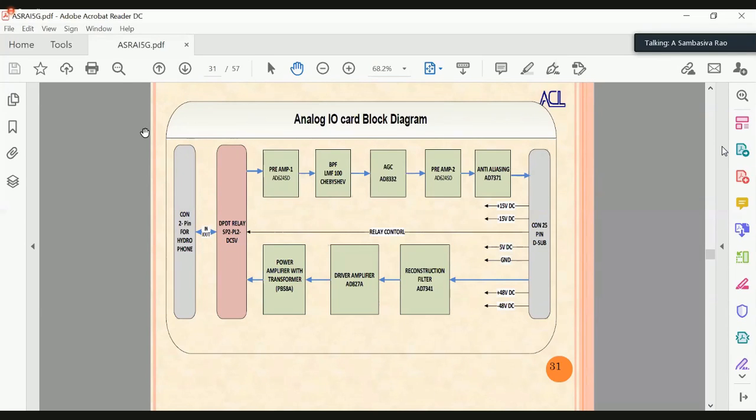Preamplifier. I have to take care in the preamplifier, such that my input to the preamplifier is the transducer, which converts acoustic to electrical energy. The acoustic transducer is a piezoceramic element. Piezoceramic is a tank circuit. It has a resonant circuit. So I need a high input impedance stage in the preamplifier, and it should be able to receive all the weak signals. The signals coming from the transducer are very weak. They are coming from the channel I am converting. So I have to be able to pick these. So it will be a high input impedance preamplifier.